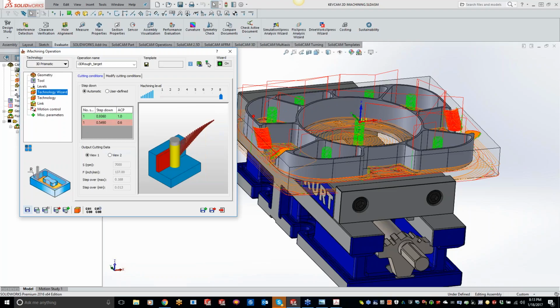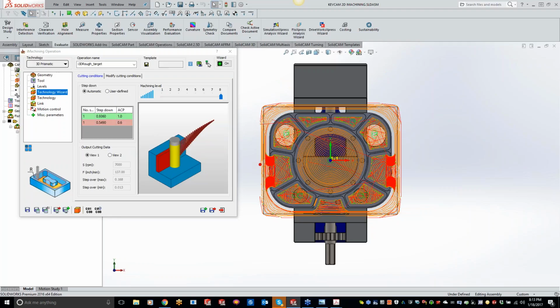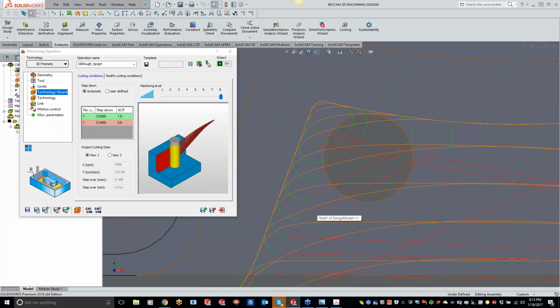You'll never see that with iMachining, because like Kevin mentioned, we're always managing the engagement angle of the tool. You'll experience it with other toolpaths, but not with iMachining. There's a lot of science going on behind the scenes. It's really interesting when you break it down.